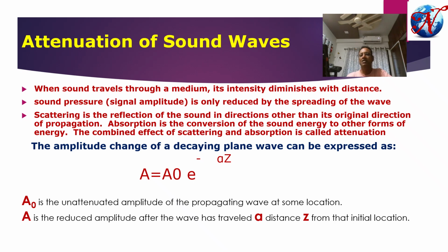Depending upon the thickness, the job geometry, or the material grain structure, we select the desired frequency such that the maximum penetration is possible. Along with that, we select the diameter of the crystal.